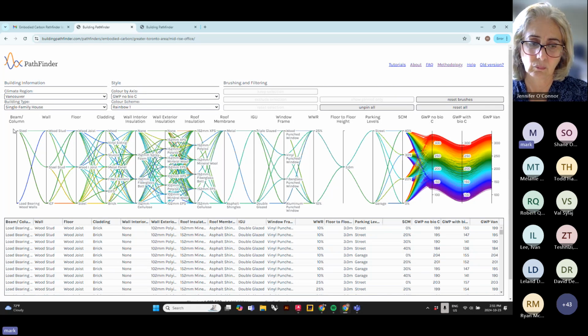And I think it emphasizes what Jennifer was saying, that it's not a detailed tool. The way I'd suggest you look at SCMs is: do SCMs make a difference? You can figure that out using this tool, and how much of a difference. Then from there, you could say, hey, that's below grade, it does make a big difference, so let's go to 40% below grade concrete and 20% in the slabs, but try to maximize it for each of the elements. That would come later in design.